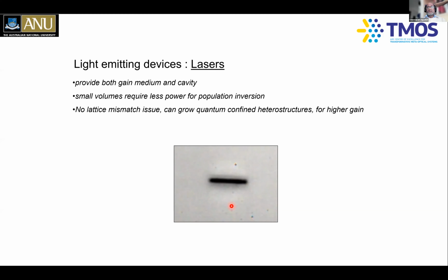So now that means you'll be able to really excite the light and use this as a waveguide, and both ends of the nanowire act like mirrors because of the refractive index difference between the nanowire and the surrounding medium. So now you can see suddenly, if I get the nanowire designed right and good quality nanowires, each nanowire should act like a laser, without having to put in any mirrors or create any further cavities and all this stuff.